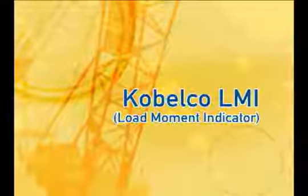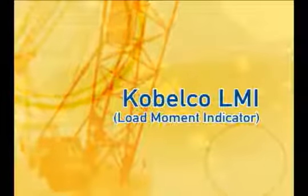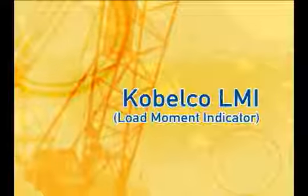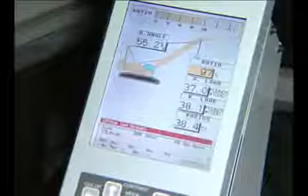This section, we'll cover the Kobelco LMI, Load Moment Indicator. This is an operational safety device that is designed and built by Kobelco as an integral part of the crane's design. This system provides audio and visual signals as the load or the radius approaches maximum limits and stops crane functions when the limit is reached.